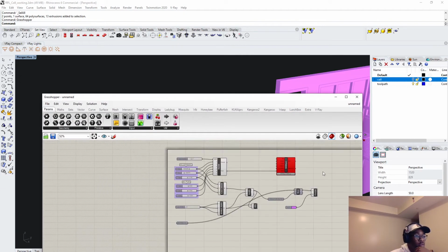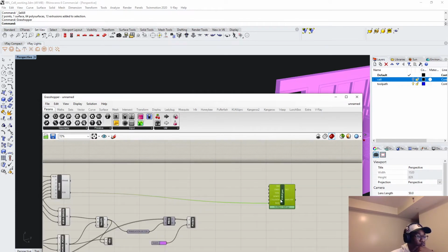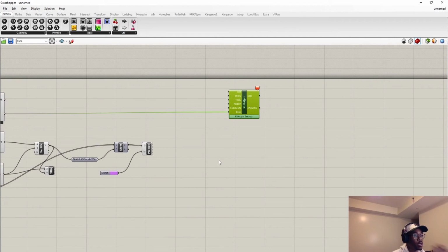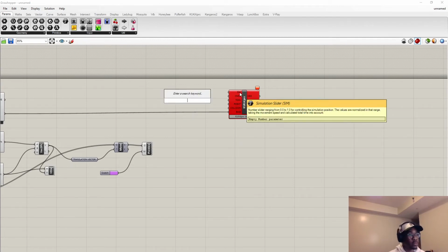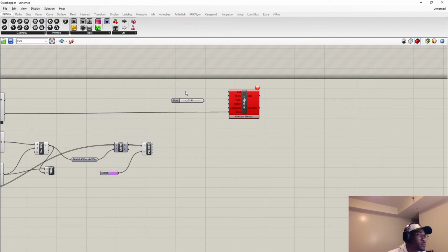Last but not least, we can go ahead and give KUKA PRC the necessary components for it to turn from red to orange. So first we need to give the simulation input a slider input. So we just type in a slider component, and automatically gives us what we need. We just need something from 0 to 1 with floating point parameters. So give that to that.